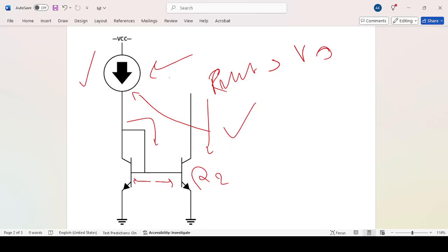So yeah, you can just copy the current, and it is important to the matching in BJT, which will be defined by IS2 and IS1. If IS2 and IS1 are equal to each other, so they are matched, and you should also be careful about layout consideration to define this correctly if you want a good match.